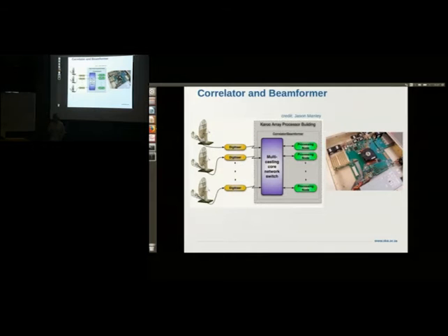And recall from the previous slide, I said that there is 34.240 gigabits per second from each antenna. So times that times 64, it produces 2.2 terabits per second. And all of that data gets plugged into multicasting switches. So there are multiple switches which this data plugs into.